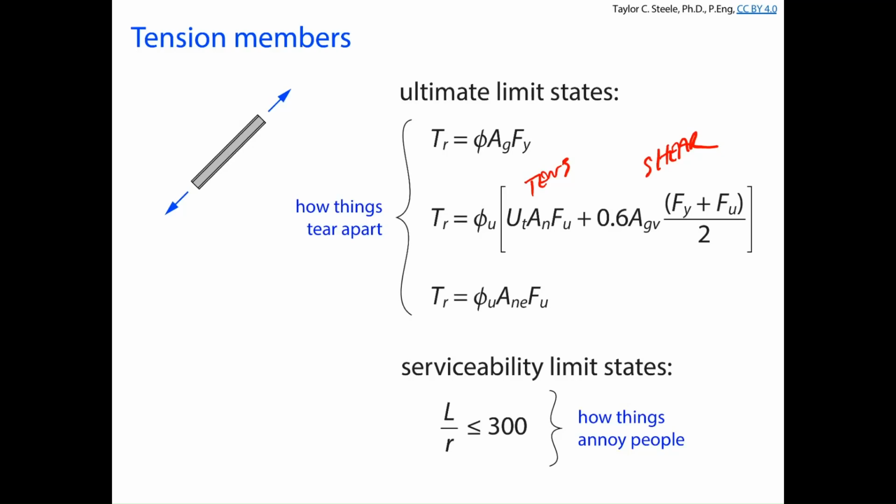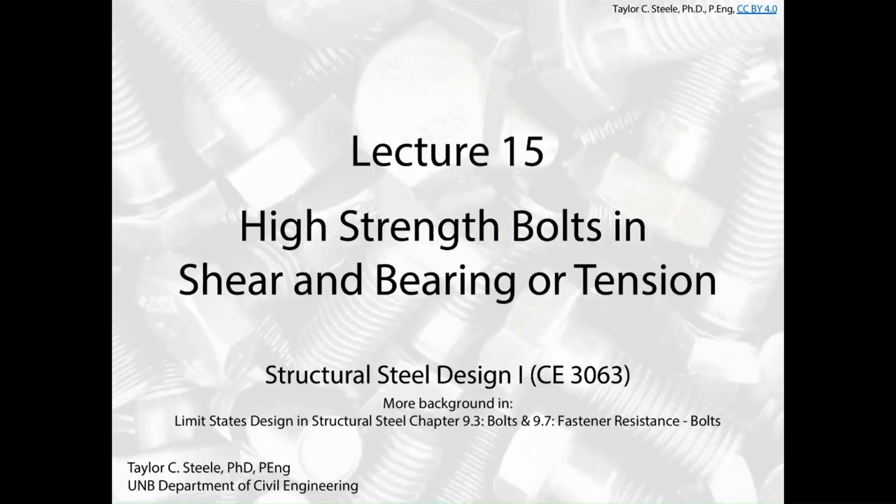To date, what we haven't talked about yet is what actually happens with the bolts that are connecting the tension members to the gusset plate. And so what we're going to focus on today is discussing the limit states associated with the actual bolts that are connecting the tension member to the gusset plate. Sometimes bolts carry loads through shear, and sometimes bolts carry loads through tension, as you might be able to guess. For the most part, we're going to focus on bolts that carry shear.